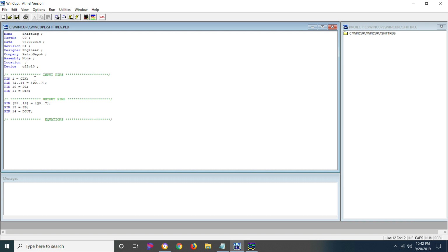Now, if the transition with the chip select goes high while the clock is still low, that's still going to be problematic for you. But by potentially using some method to read the outputs from the Q pins, you should be able to tell whether or not it actually latched.